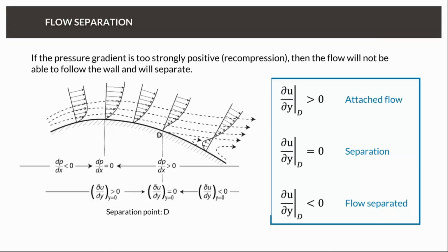But as soon as you start to create divergence, so a tube that's expanding, expansions of tubes or expansions of walls, then again conservation of mass makes the speed get lower. And then the pressure is increasing again, and you always have the risk that you separate on an expanding wall.